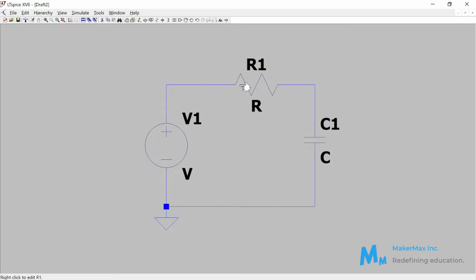So I want to see the instantaneous behavior of the circuit when the voltage source is connected to the resistor and capacitor. If I don't do it this way, if I say that the 5-volt source is connected and we just run the transient analysis like we used to for the resistance circuits, then it's not a justified circuit, because that would assume that this voltage source has been connected for quite a long time.